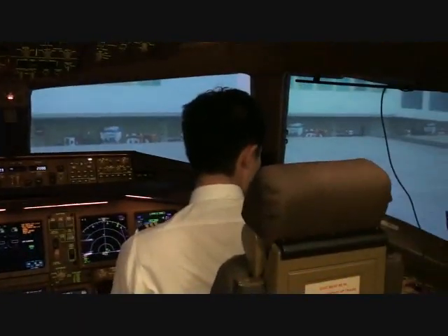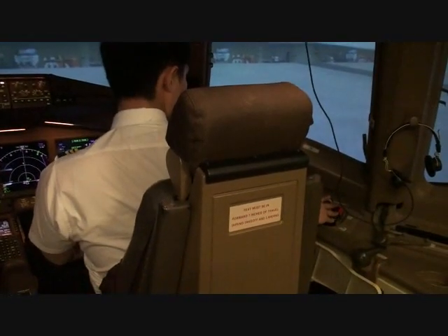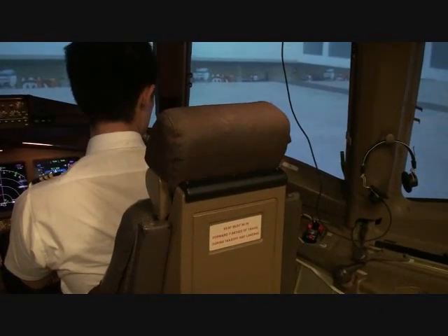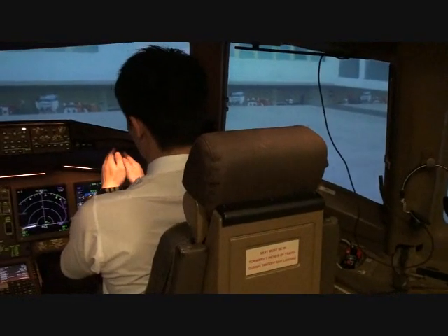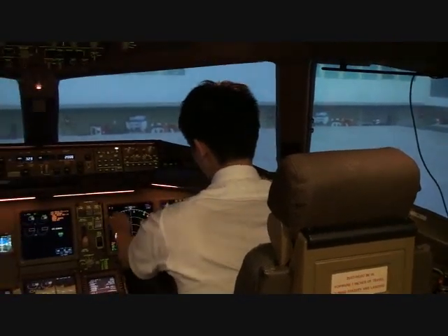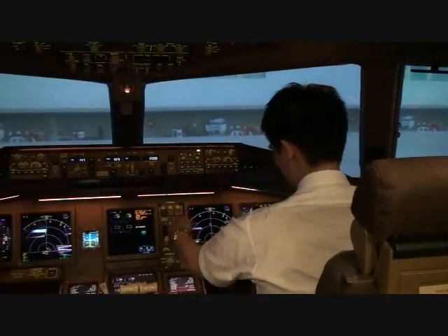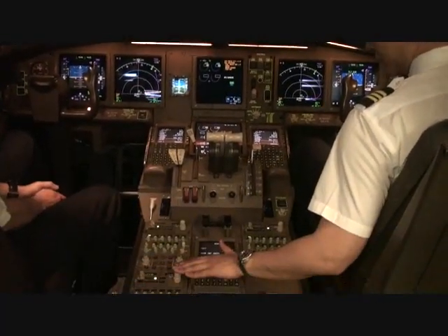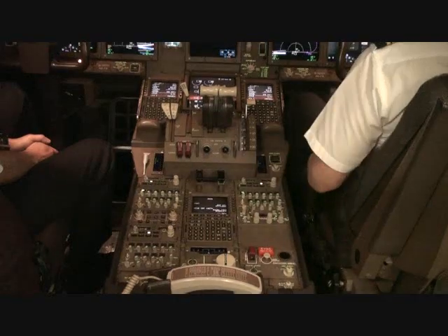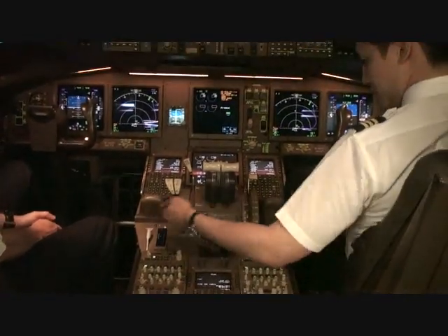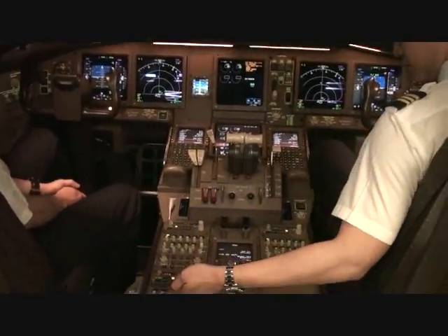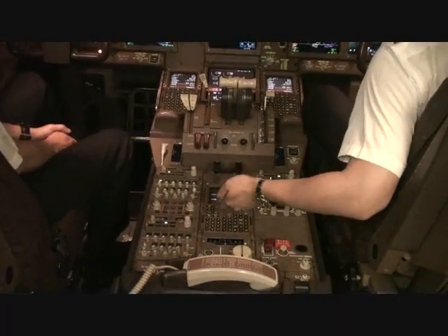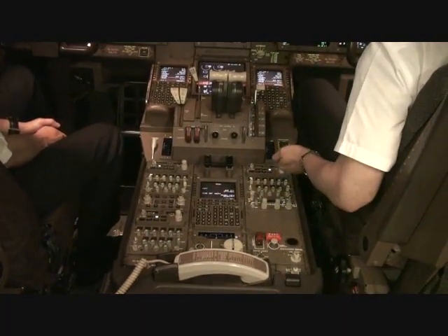Then, starting with the flight director switch on the MCP, goes left to right, and then back over on the oxygen panel to come round towards the front, across the flight instrument panel, and then down towards the center console. The center console in 3 sections, starting at the top, left to bottom, center, top to bottom, right, top to bottom.